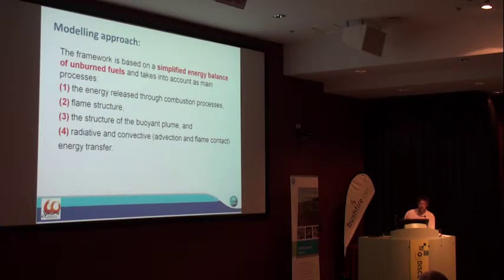It has to do with this energy in the fire making the flame standing, and the flame structure in its angle is always a balance between the wind and the buoyancy in the fire. When we start an experimental fire, we don't have much buoyancy yet because the flame front is thin. So the wind is really driving the propagation. But as the fire builds up, we have more buoyancy, and so it changes the flame structure and the heat transfer. So we need to understand that.